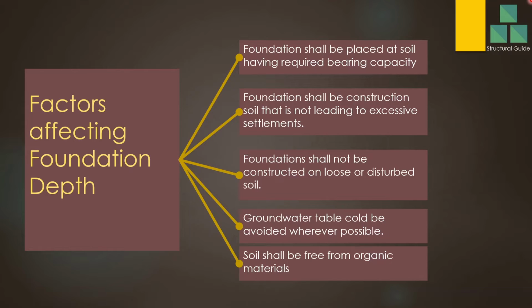Therefore, you have to consider the ground condition very carefully during the construction. Even though the depth is determined in the design, whether 3 feet or 1 meter, the design or the drawing specifies that at site you have to check and make sure those conditions are met. The actual condition may not be reflected in the design documents. Therefore, the site engineer must be aware of these facts when doing the construction of footings.